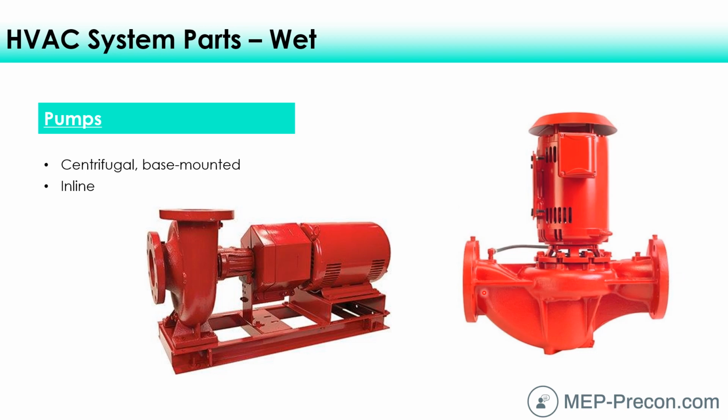Now, it's kind of a misnomer a little bit. The way that it's piped is in line, but the way that it works is still a centrifugal pump. If you look at this here, you can see the manufacturers designed this to come in and make a hard 90-degree turn inside here, and then it spins around. So really, it's a centrifugal pump, but just cast in a way that makes it easy to install in the field in line, where the inlet and the outlet are in the same plane.